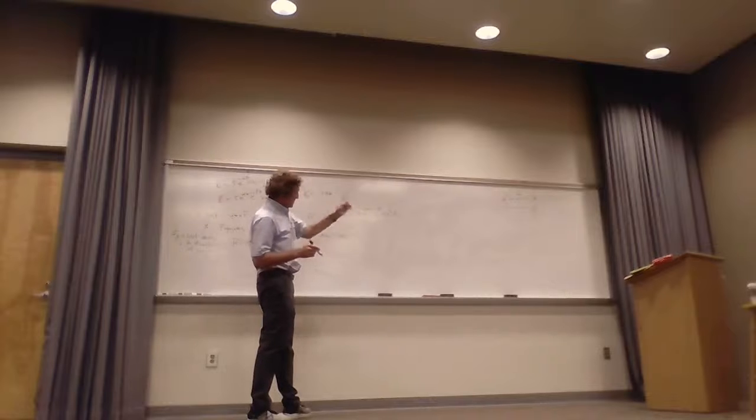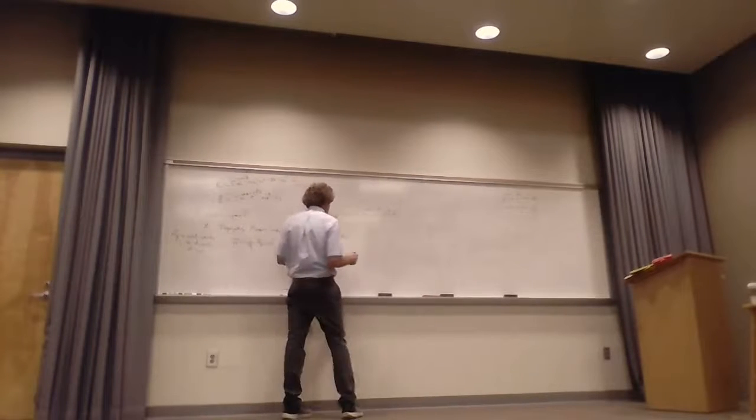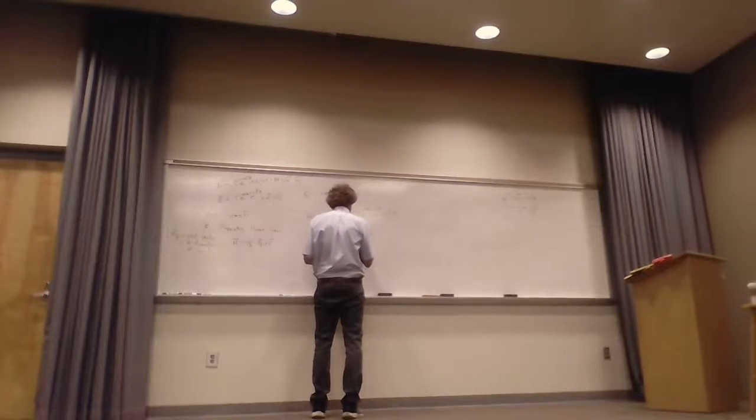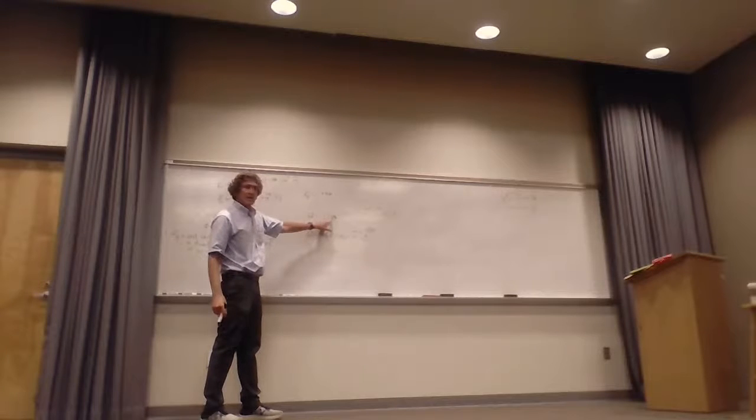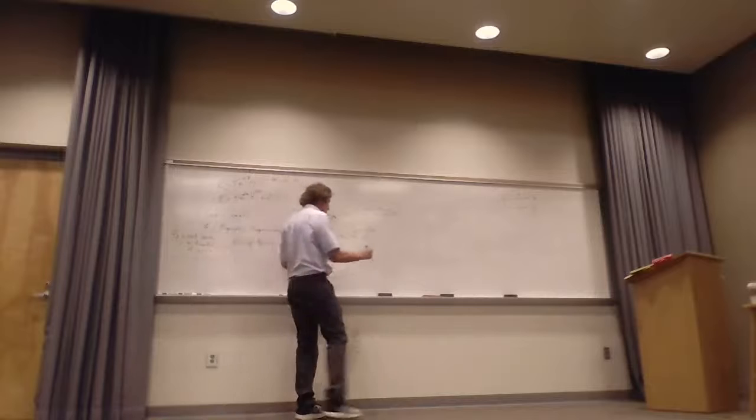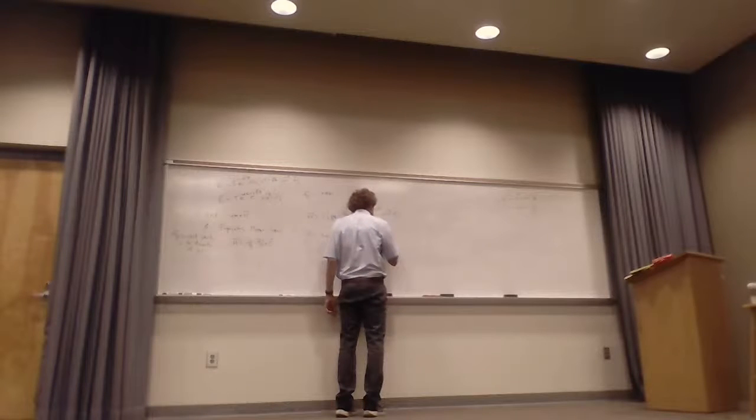And then, going the other way, I'm still going to have e to the minus alpha z, e to the minus j beta z. I know they're both about 4,000. There's one last thing. You see this angle? That's e to the j 45 degrees, or e to the j pi over 4 radians. When we take 1 over that, it becomes e to the minus j pi over 4 radians.